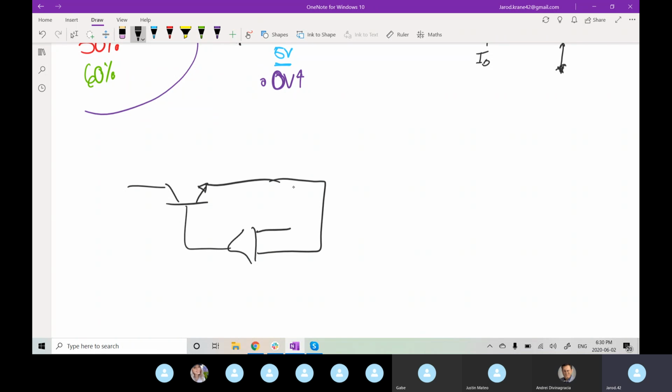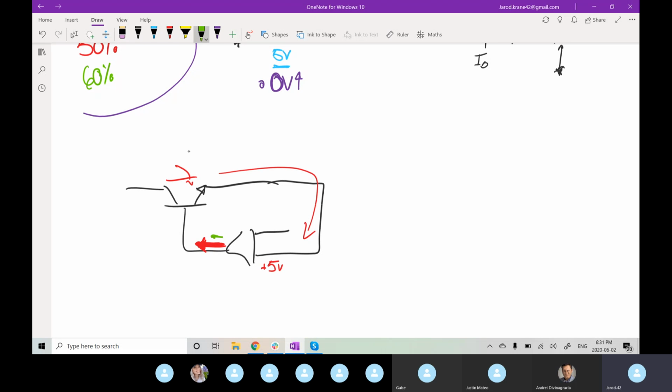So initially you have nothing, so it'll send whatever large current to try to pull these together. Once we're able to allow some current flow, we're now going to see some voltage, and it's going to realize maybe it's now over 5 volts on this pin. So it's going to decrease the amount that it's letting through.